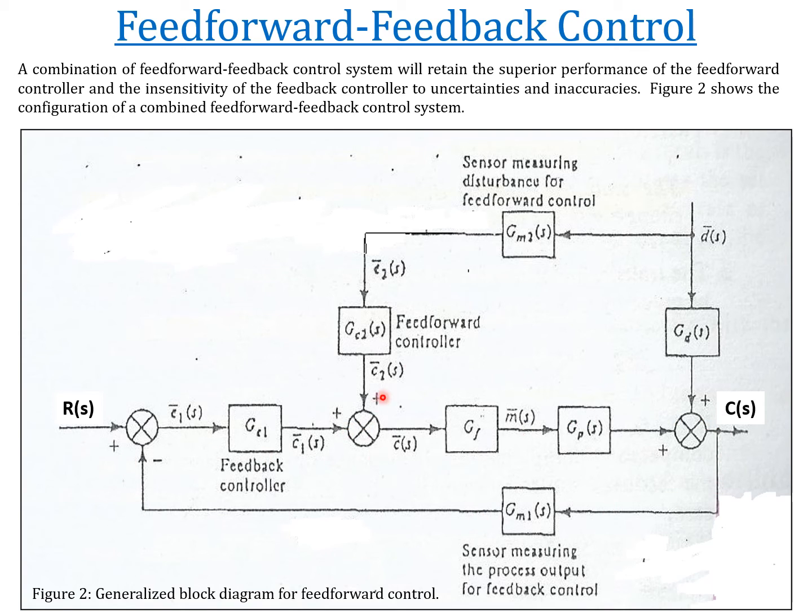So you have both, the feedforward controller mainly to reject the disturbances, and the feedback controller basically to try to bring it to the set point that we want at the same time. So it acts both. You should be able to get some good set point tracking, and also you are able to reject the disturbances that come in from the system using this combination of feedback and feedforward system. So this is where they have the advanced method.